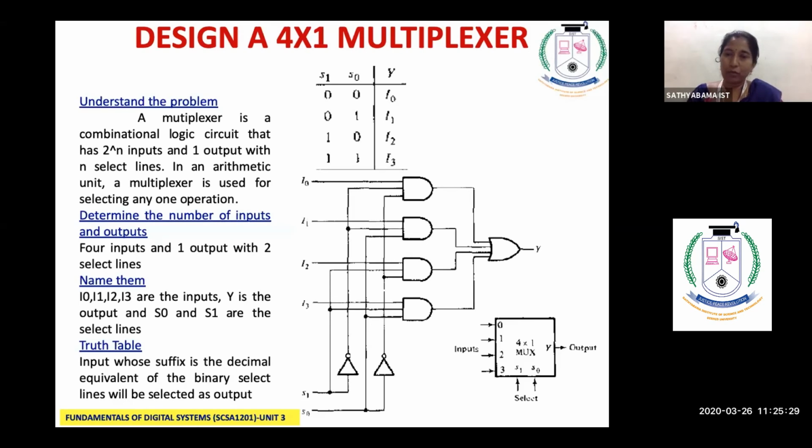So if we do not use a subtractor, then your question should be, how will we perform subtraction without using a subtractor? For that, you have studied the answer in your first unit. Instead of performing subtraction as subtraction, we can perform subtraction as 2's complement addition.